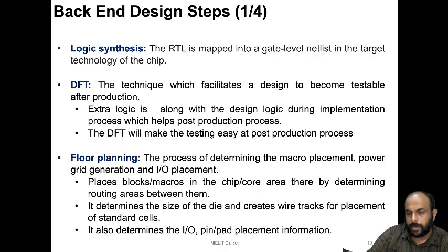You have a particular RTL design, and we synthesize it for a 90 nanometer technology. The resulting file will be substantially different if we try to synthesize it for a 45 nanometer technology. It will be substantially different if you are trying to create a netlist for a field programmable gate array or some other programmable logic.